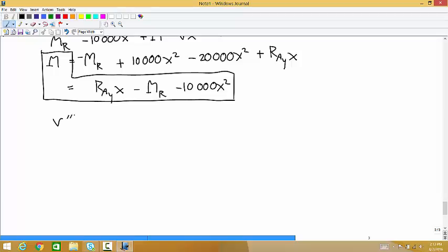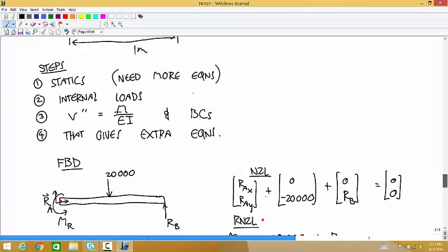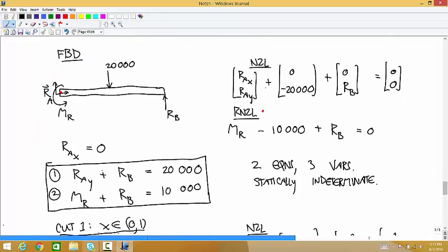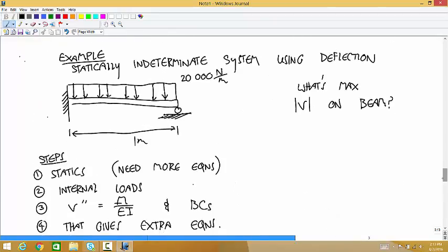And the deflection is equal to, oh, I didn't give any, did I give values for this, the material values? No, sir. Let's pretend I did. And let's pretend that the ones I gave you were Young's modulus for steel, and an area moment of inertia of 1.0 times 10 to the minus 7 meters to the fourth.